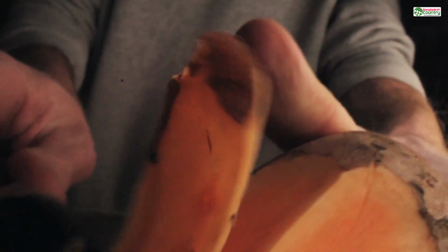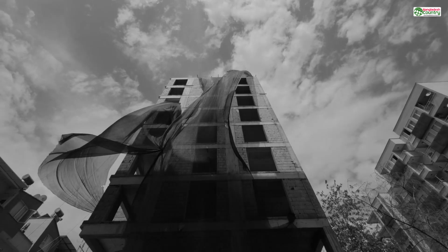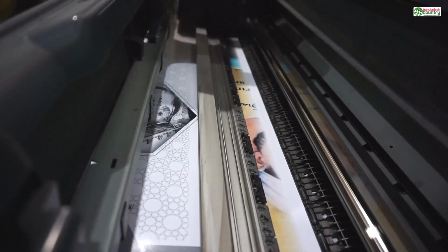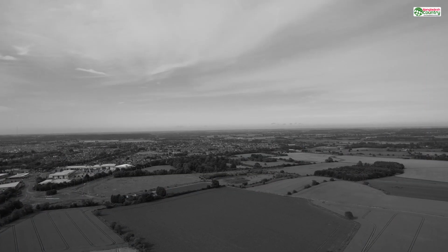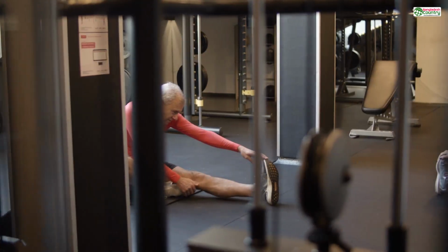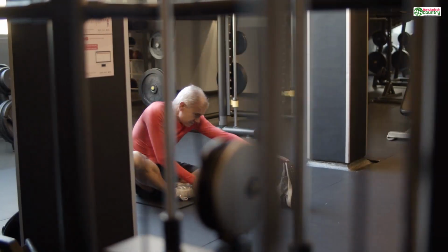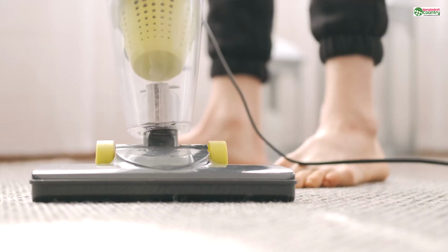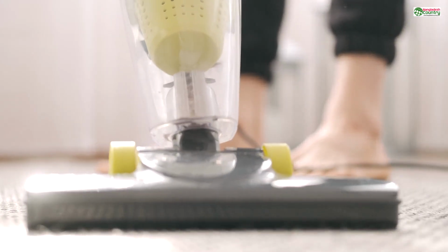Imagine a solid resin part being printed. It's built layer by layer, with each new layer being cured by UV light. When you print a large solid cross-section, two bad things happen. First, you generate a ton of heat from the chemical reaction of the resin curing. This internal stress can cause cracks and warping days or even weeks after the print is finished. Second, and more dramatically, you create a massive suction force. As the build plate pulls up to create the next layer, it's trying to pull this wide, flat, cured layer out of the vat of liquid resin. The suction can be so strong it literally rips the part off the build plate or separates the layers mid-print, resulting in a catastrophic failure.